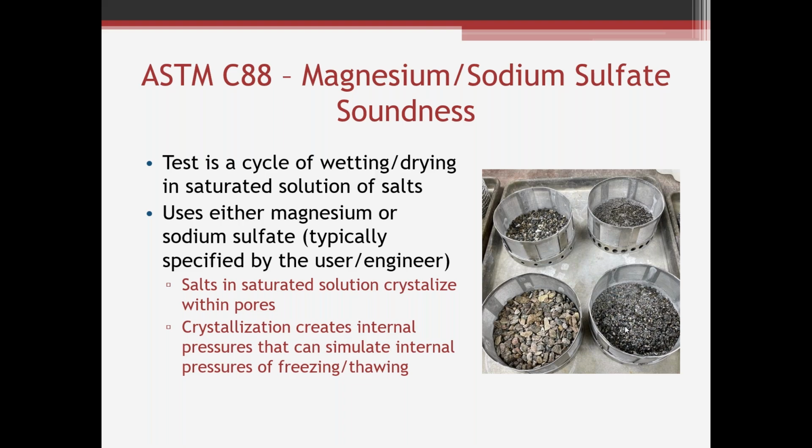Remember, there's the absorption test, so these aggregates have some absorptive property. As the solution crystallizes, that creates an internal pressure that kind of simulates freezing and thawing. So this test at the end of the day is kind of a mass loss. We do the soaking, drying, weigh it before, weigh it after, and hopefully there's not a lot of loss of material.